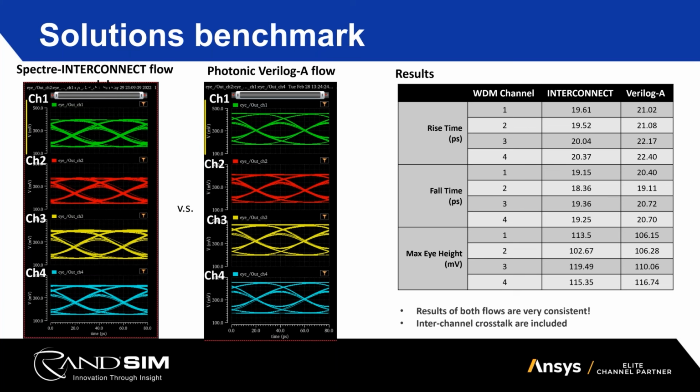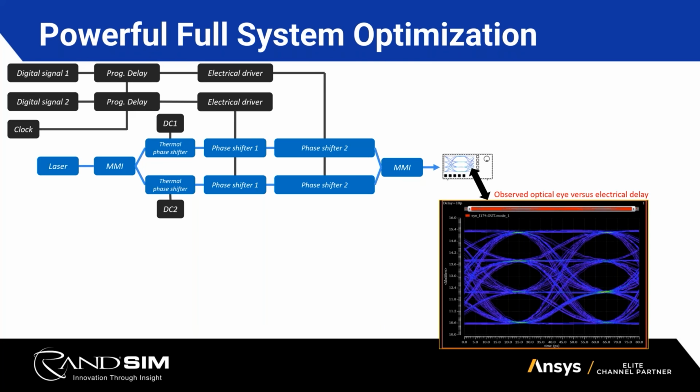The difference is that the INTERCONNECT co-simulation workflow runs INTERCONNECT as an engine and also Spectre as an engine as well. For the Photonic Verilog-A design workflow, all models are SPICE models, so users only need to run Spectre as the solver. So talking about the co-simulation, it's a very powerful tool for system optimization, and it can actually